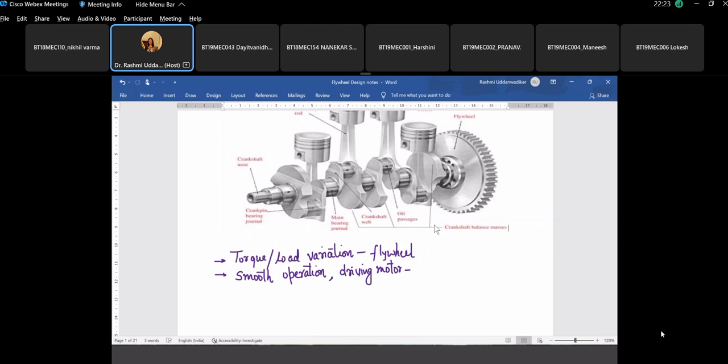Since we have this flywheel, which is an energy storing device, it can take into account the peak requirements or the peak demand. We can still work with a motor taking care of the average demand, and the excess torque required or that speed requirement can be fulfilled with this flywheel, which we also call an energy storage device.